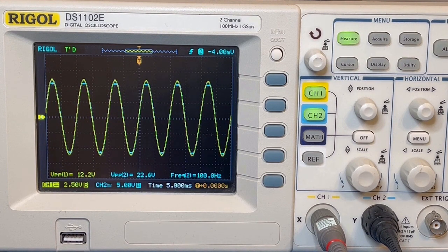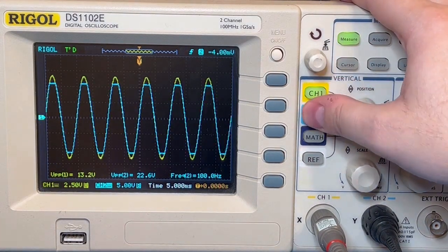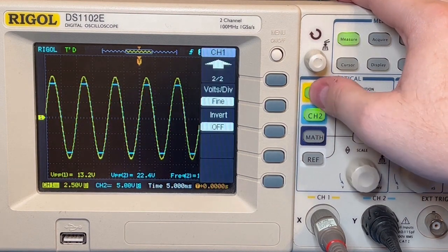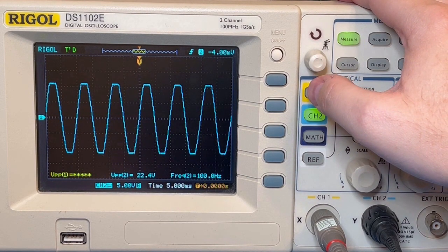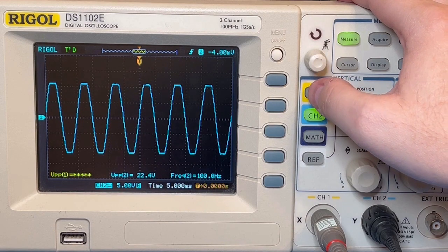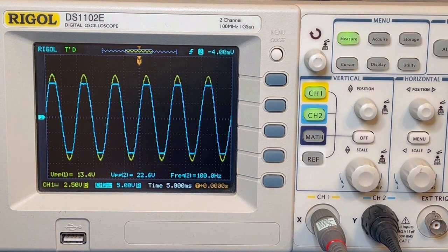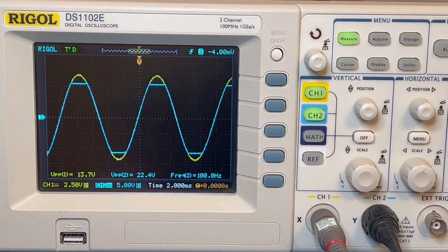So at about 22 volts, we see some flattening in the output. The input looks clean, just as before. The output looks like the tops of the sine wave have been chopped off. It's flattening because it can't go any higher or lower than a certain point near the rails. Even with higher input voltages, the problem persists.